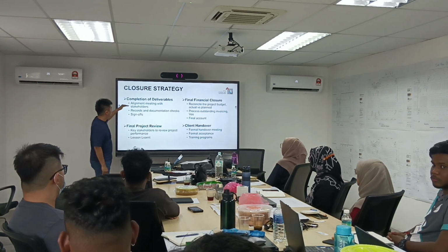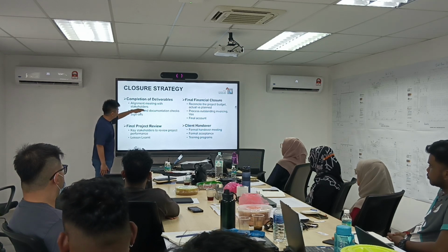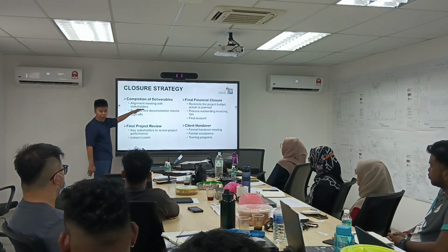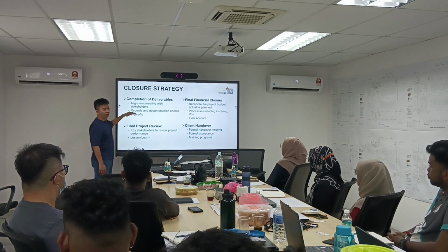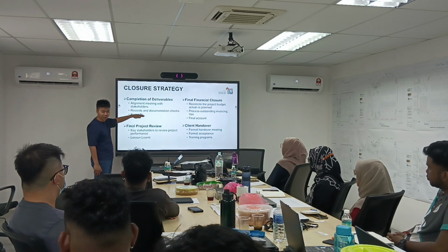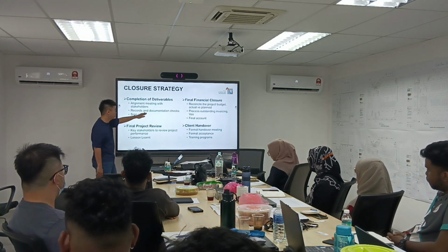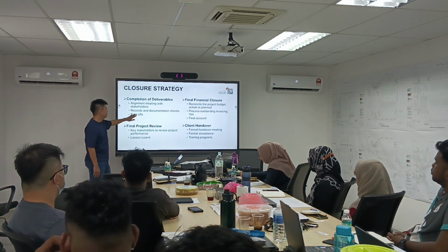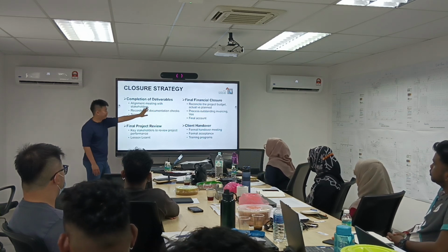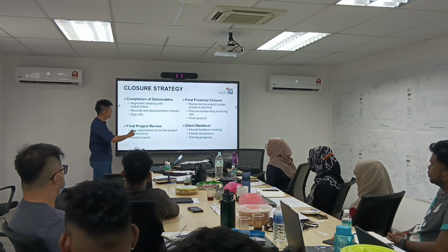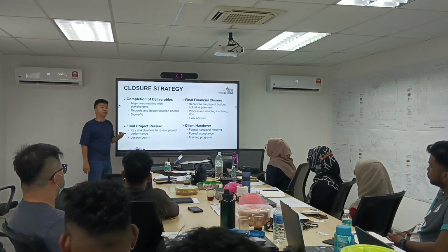Okay, so for day 2, I hope to see that we have this alignment meeting before we hand over, which is in October. And then of course, before handover, we also need to prepare all our records. We need to export the Aconex drive. We need to export all our ITPs, all our CX documentation, everything. And when we hand over this thing, and when we align, I would call this a handover matrix. We define all these handover matrices, then we ask them to sign off.